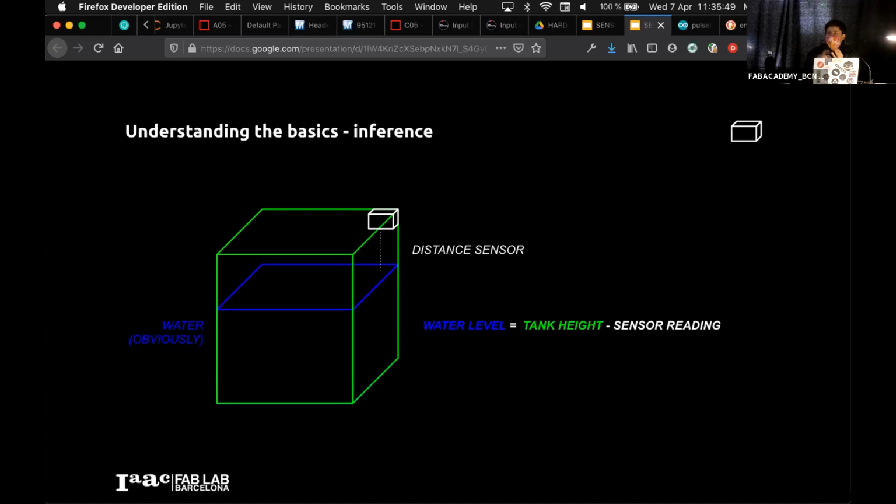So ultrasound, perfect. Another one is PIR, an infrared sensor. It depends. PIRs, for instance, are used in bathrooms when you don't want to touch the switch. There's a light detector that is a PIR sensor. It is a motion detection sensor, and you could use that as well to detect distance. PIRs are more expensive, but ultrasounds, for what we do, are more than affordable.